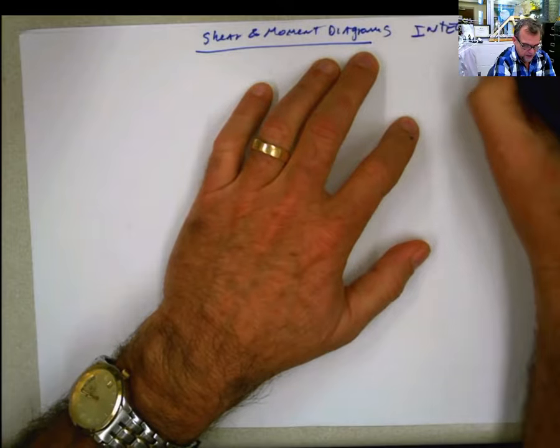And I'm going to explain to you what that is. So the shear is the integral of the load. What is the value of the load here in AC? I'll give you 5 seconds. 5, 4, 3, 2, 1. Very good. You answered correctly. There's no load. It's the integral of 0 dx plus c.